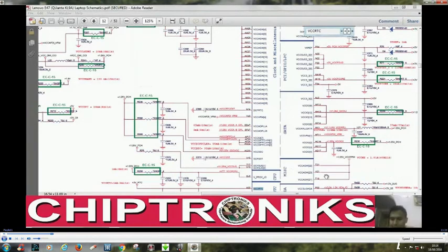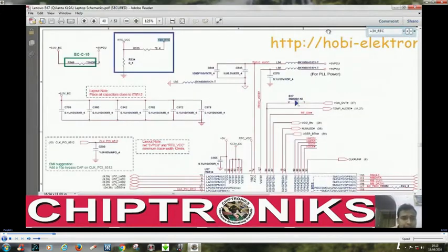So the very first step while checking this HM67 kind of board is to check the VCC RTC, okay? Now we have to check here by multimeter whether this plus 3V underscore RTC is coming or not, whether this plus 3 volt is coming or not. If it is not coming, now where do we have to go? We have to search this plus 3V RTC. Obviously it would be coming from the battery, the RTC battery, but here we can search the plus 3V RTC.